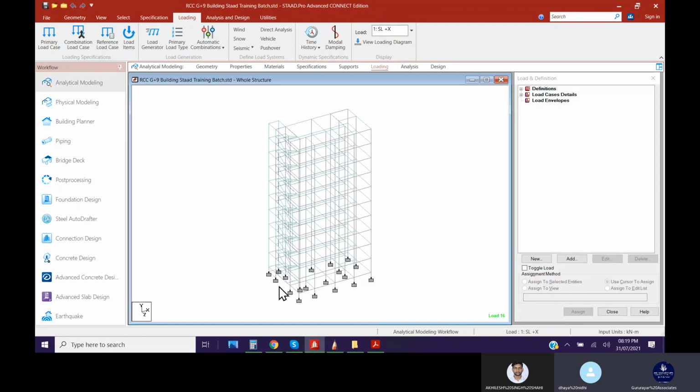If you are using heavy bricks, then all become very big. Beam, column, footing all become very big sizes. So if the size becomes smaller, it means it's minimizing the cost, no? Cost minimization. For that purpose, they use AAC bricks.